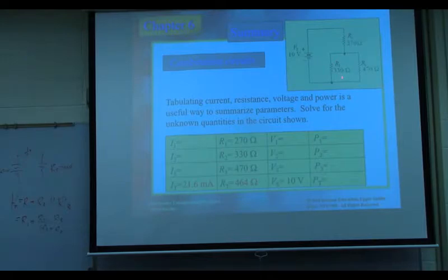Now you need to separate. All the voltage is the same. We can use a current divider to do this, right? But later we will find we have a better way to do this, okay? So if you write this one, I1 will equal 21.6. But these two, not. We can use a current divider to get each one. Make sense? Alright. Now look at this one. Next one looks like we should calculate the voltage here. Can we? Because we already know the current here, right?